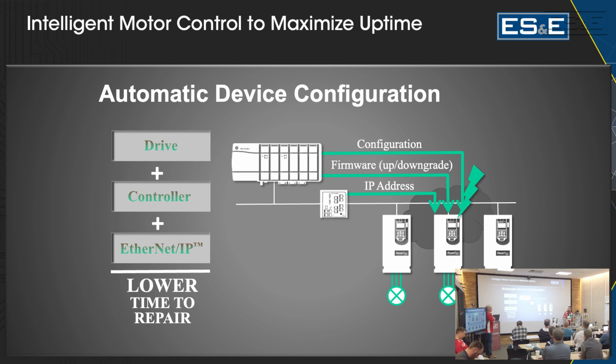From there, we're going to have what's called a firmware supervisor. That's actually saved on an SD card, the non-volatile memory section on our PLC. We'll save that program file, and what that's going to do is flash our firmware based on our settings in our controller properties. We can choose to enable that or disable it in our controller properties. If we choose exact match, that will flash up or down depending on the program that's saved on that SD card.